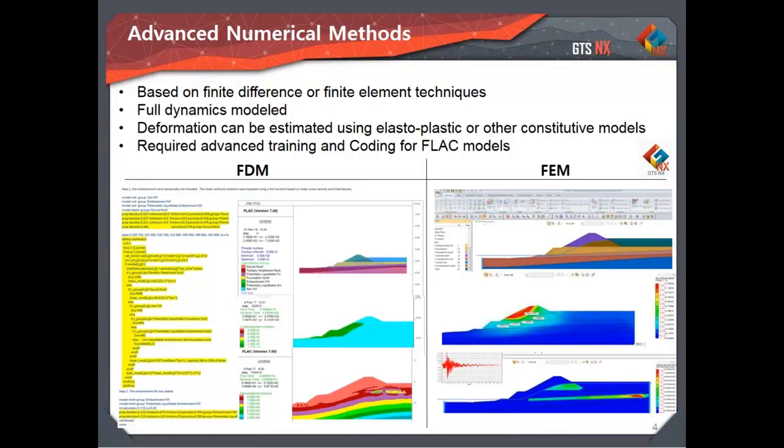the alternative is to use finite element software like Plaxis or MIDAS, in which case we will show the procedure, and you will see that it's a much more hands-on approach. The interface is CAD-based, so it's very easy to start even from scratch, to draw, to mesh, and everything. We'll also see extracting the results, especially the deformation results and the important results for liquefaction: the pore pressure and which layers have become susceptible to liquefaction.